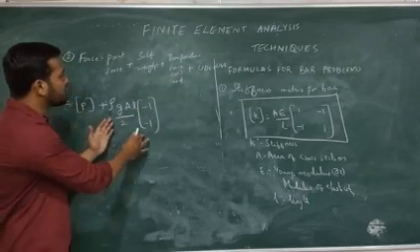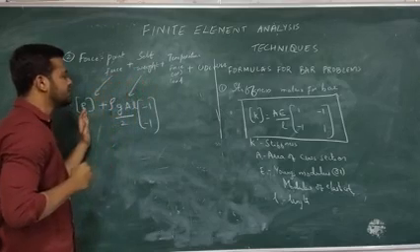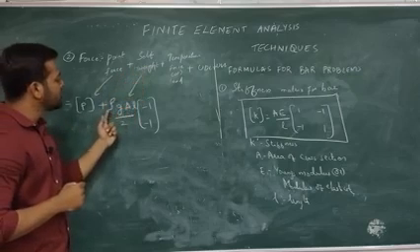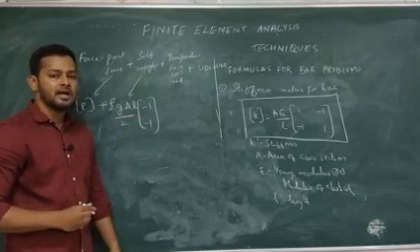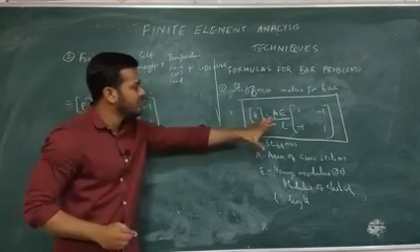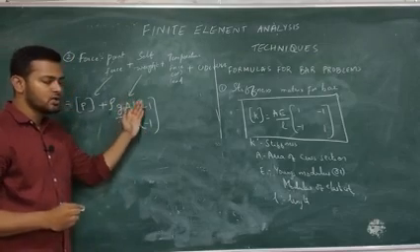So that's the formula for self weight. This is point force, it's a direct value, we don't have any formula for that. So the self weight formula is rho g A L by 2 times the matrix with minus 1 and minus 1. This is also a matrix here, along with the stiffness matrix. I will explain how we are using these matrices.